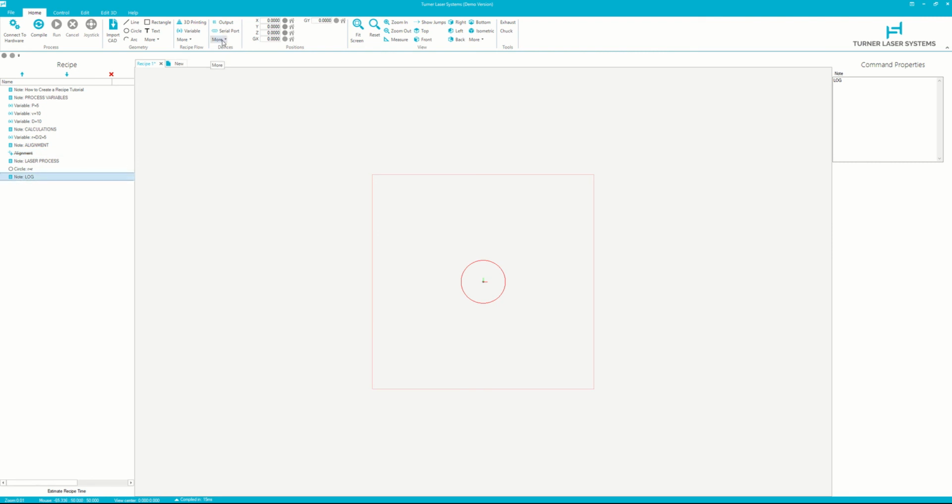Log would be really useful, particularly if you're running this recipe many times and you have different process parameters and you want to save them all and then look at what your parameters were at different times of the day. So let's go to export data, which is used for logging, and it will save this into a text file. You can put the text file name here.